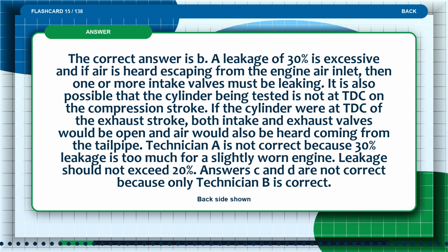The correct answer is B. A leakage of 30% is excessive, and if air is heard escaping from the engine air inlet, then one or more intake valves must be leaking. It is also possible that the cylinder being tested is not at TDC on the compression stroke. If the cylinder were at TDC of the exhaust stroke, both intake and exhaust valves would be open and air would also be heard coming from the tailpipe.